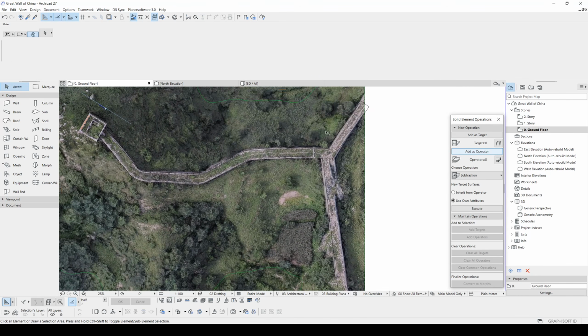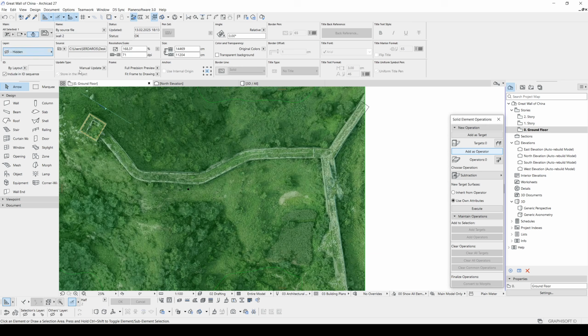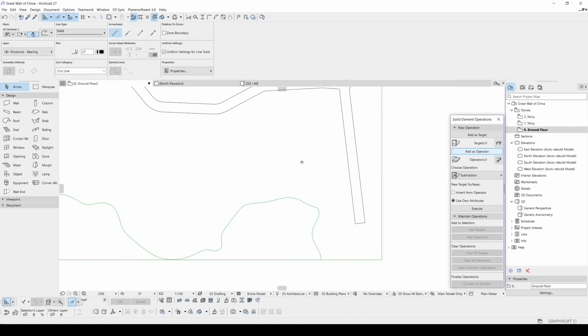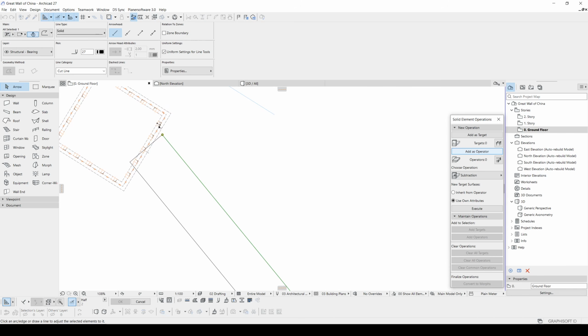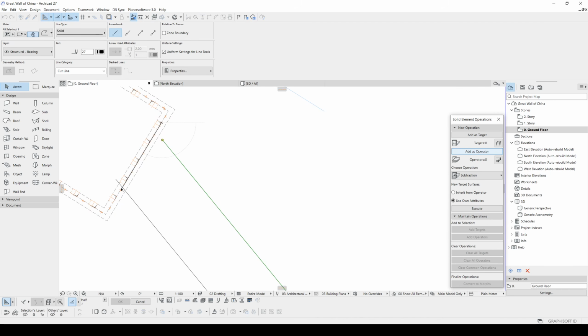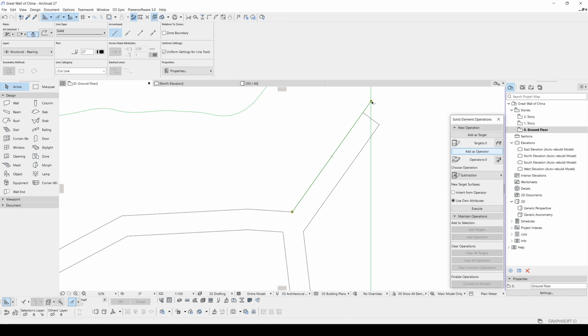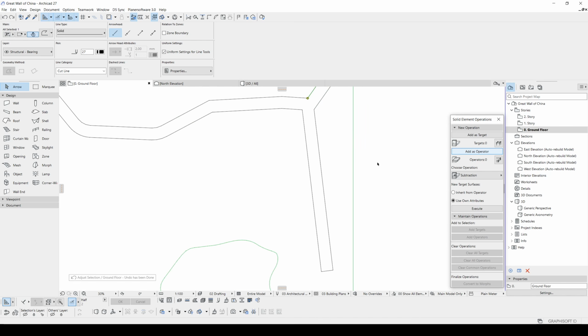After deleting inside, as you can guess, we will just fill inside with the mesh tool. But before that we will make this hidden to see it better and fix the remaining shape. We are trying to make this closed shape. After doing some little adjustments, this will be ready. For this purpose, you can use split and extend commands. They are very useful. I'm gonna split this from here, or I can adjust this to the wall, just like this. For this corner, we can fix this like this, or we can leave it like so.